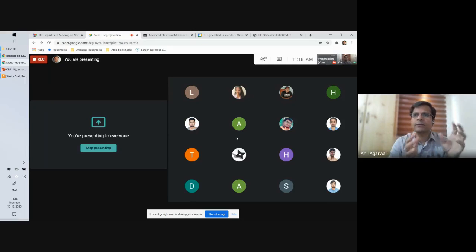What does that mean? So if your A is half, your D will be half. If your A is twice the force, your D will be twice the displacement. Agreed? So that is superimposition. If you have A1 is equal to S D1 and you have A2 is equal to S D2, then automatically A1 plus A2 will be equal to S multiplied by D1 plus D2. So as soon as you write that equation, all these things automatically become true. So that equation itself has the superimposition built into it. You follow me?